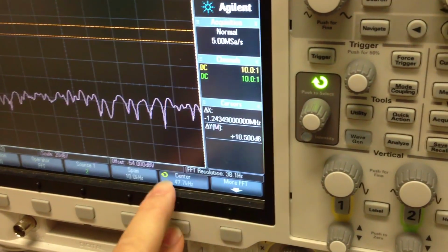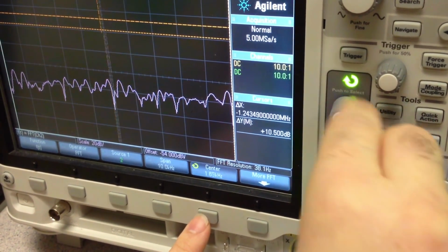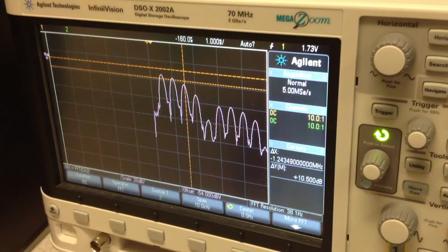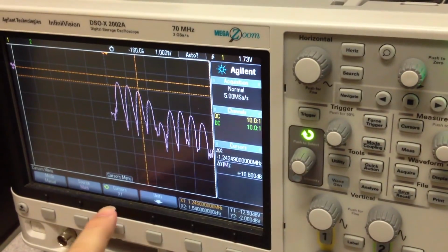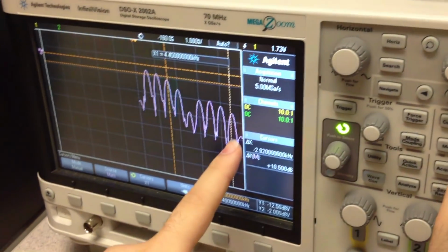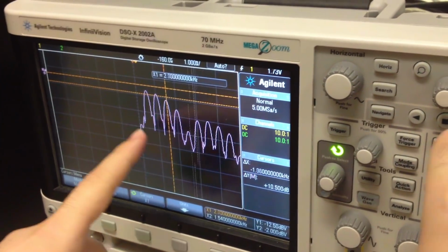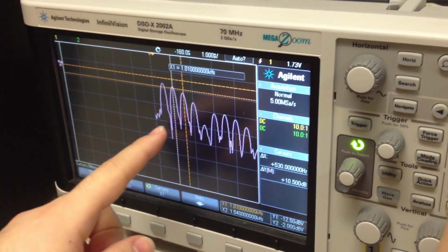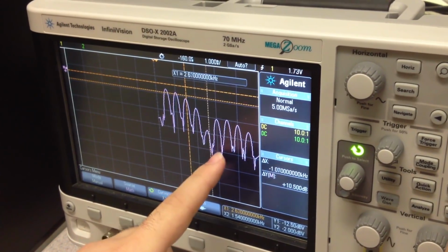This mark is the same as this mark. Okay, the same pins, but they are a bit attenuated. Again, we get cursors. We get the X cursor, so we check the frequency space. Yes, the frequency is located as we expect. That's 0.5K, that's 1K, that's 1.5K, that's 2K, that's the 0, then 2.5K again.